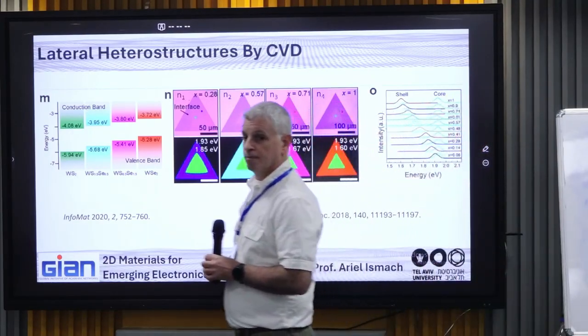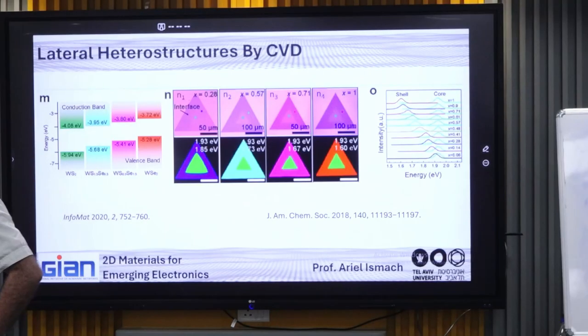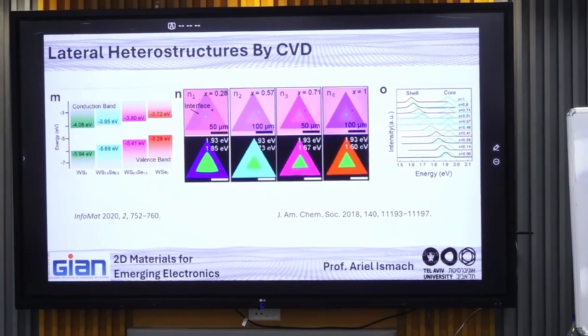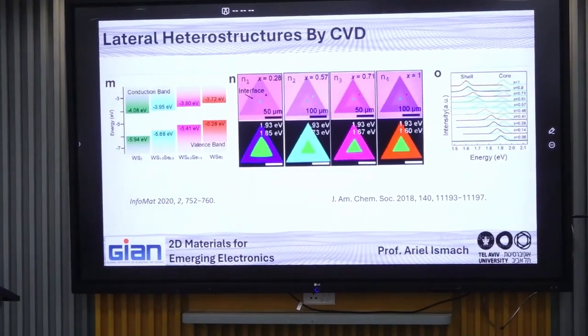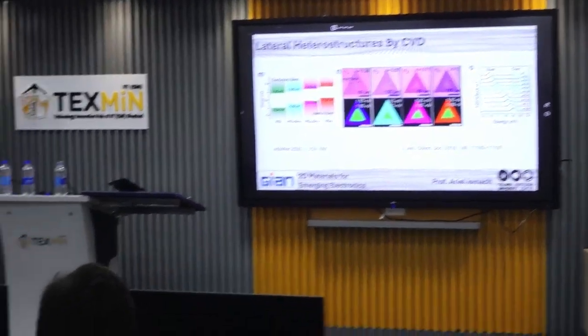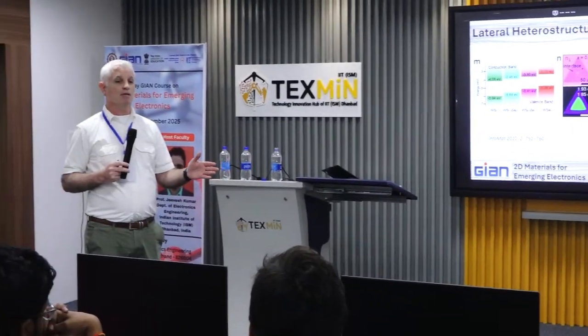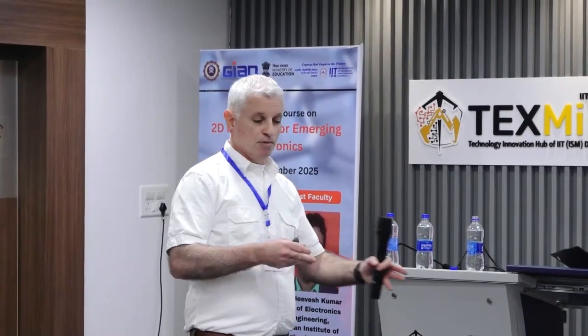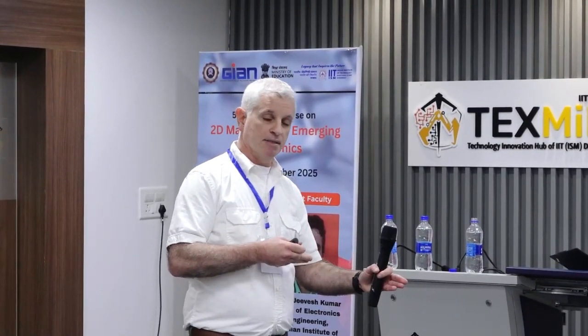How to manage that composition in CVD? It's very hard. This is something where you can only estimate the composition. So you change the composition during the growth. For example, you can do it in many ways, even with the powder precursors. You may set a manifold in which you flow selenium and sulfur separately. Then you switch between them.